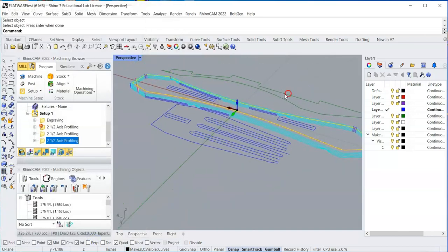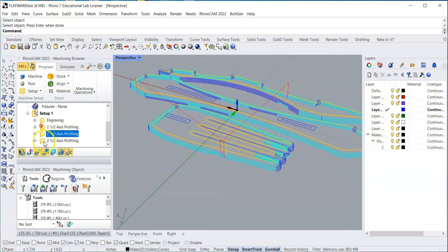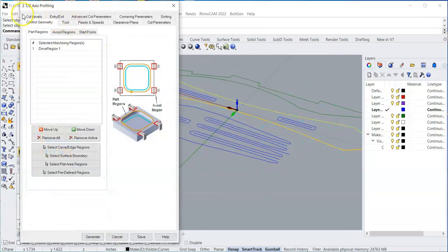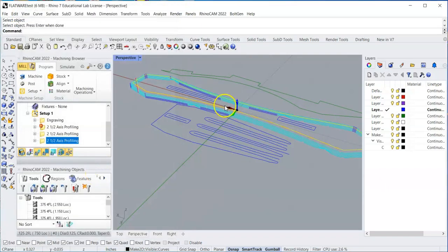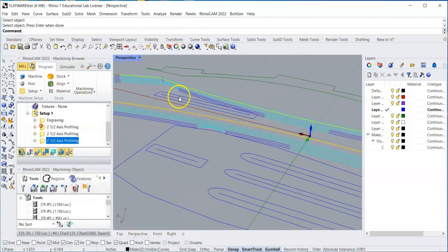And then, if you said, I want to cut it in a different pattern or a different way, that's how you do it. And that would be like where you would go in and change from outside to inside and everything. Yeah. You go in and change inside and outside if you were doing that too. Yep. The only thing to remember is, see, we didn't put bridges. So that's why I didn't put bridges on those inside tabs.